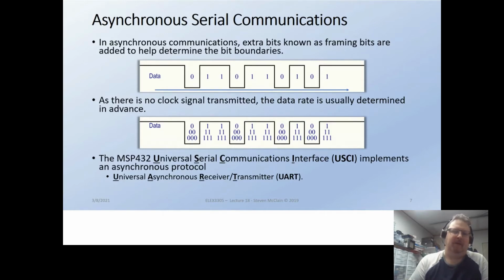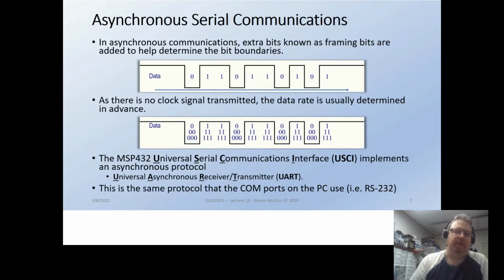We don't really know where the 1 is in there. It can be sort of anywhere. This is the data we got showing up. We see this is the start bit, and really it gets fuzzy as to where to call a 0 and where to call a 1, because we don't have a clock anymore.